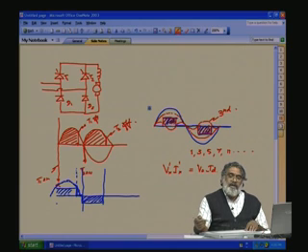What will happen if you do that way? Is there any advantage here? Let us study how we can use it. See here, it is not the current harmonics, we have the voltage harmonics. Whenever the current harmonics are there, there should be a voltage also there. So, voltage harmonics we should shift to the high frequency side.